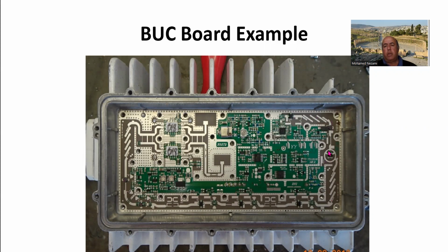You can see that's clearly the mixer in here. And then the IF is somewhere in here. All of that is an IF section with controller and all that. We go into the filter, an edge coupled filter, and then we have a whole chain of amplification and filtering up to this point here, where we have one of the filters in here, and we create a quadrature signal in here. So these are the two devices in here, somebody handwritten over them.